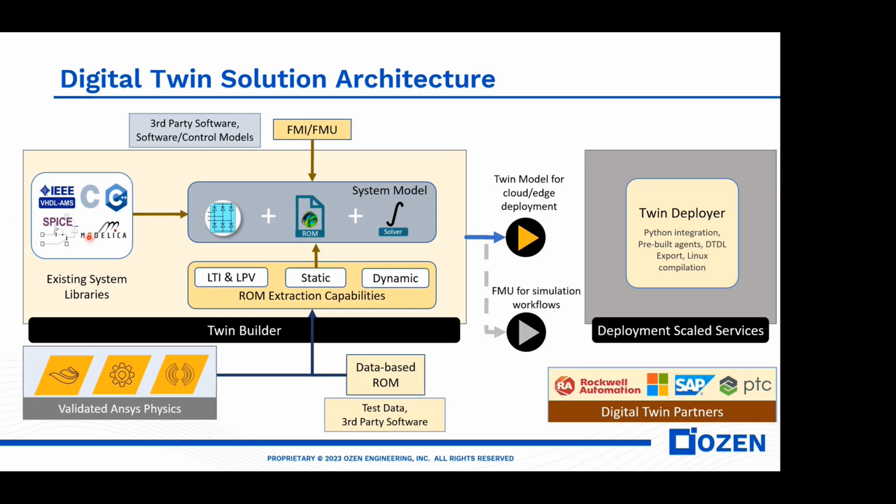So if you want to create a feedback loop of a system, if I have a tank and I'm filling water into the tank, and there is a feedback system which is looking at the level of the tank and then asking the pump to either operate or stop, that will be a feedback loop. And that kind of loops you can create within the Twin Builder platform.